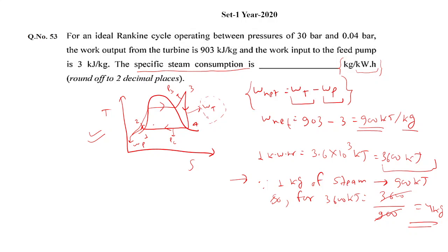Okay. The Rankine cycle is the ideal cycle to produce work in a power plant, right? Our aim is to achieve this cycle, but actually there are some losses. In that cycle there are 4 processes. From 1 to 2 it is the pump, where we increase the pressure of the liquid from lower to higher, and from 2 to 3 we give heat in the boiler, and it is expanding here, higher pressure, higher volume.